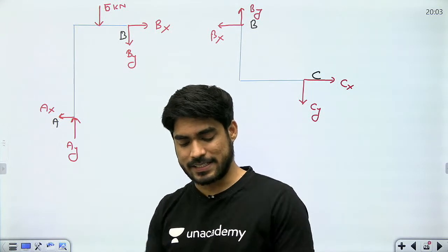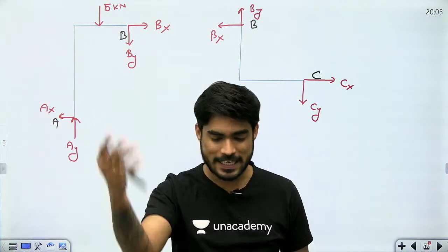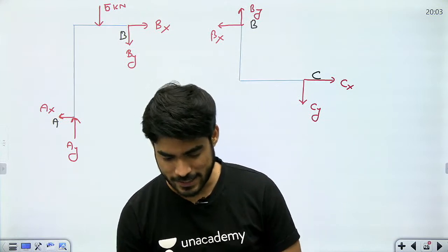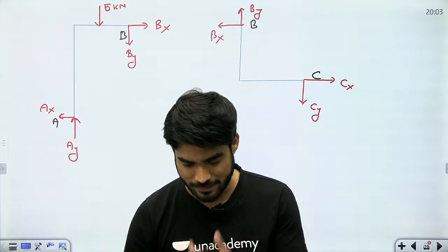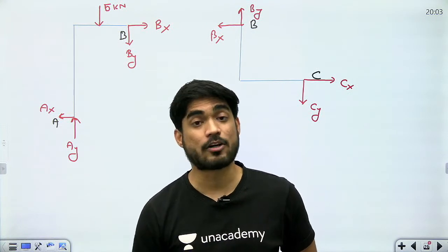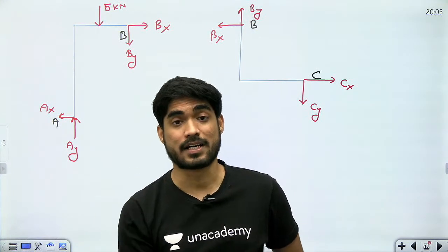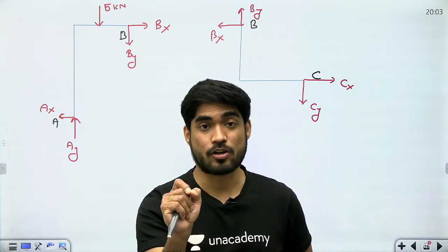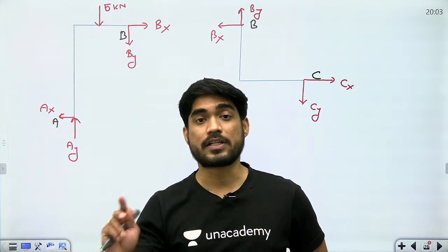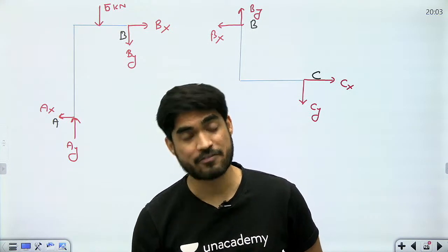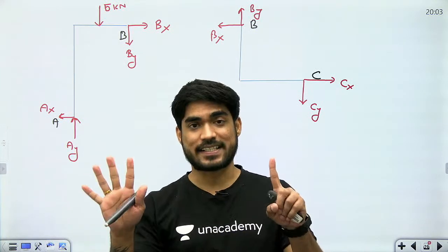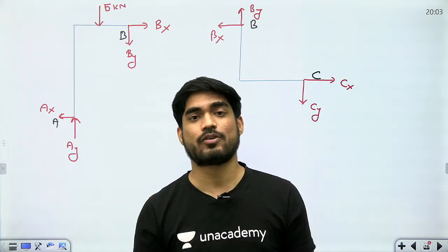Naga Pavan is saying 4 equations for each member. Yes, Nitish, very good. Hemant, very good. Karan, very good. Vikas, very good. There are 3 equilibrium equations for every member: summation of fx, summation of fy, and summation of m equal to 0. So total how many equations do we have? We have 6 equations. So we have 6 unknowns and 6 equilibrium equations.